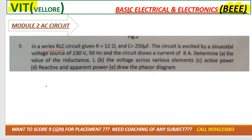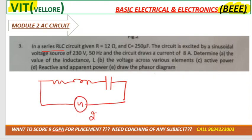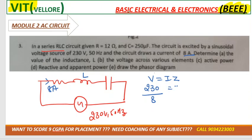See, in a series RLC circuit, the circuit is excited by a 30 volt, 50 hertz supply, right? Current is 8 ampere. Calculate L. So V is equal to IZ, 30 over current 8, we can get Z. Z is equal to root of R squared plus XL minus XC whole square.